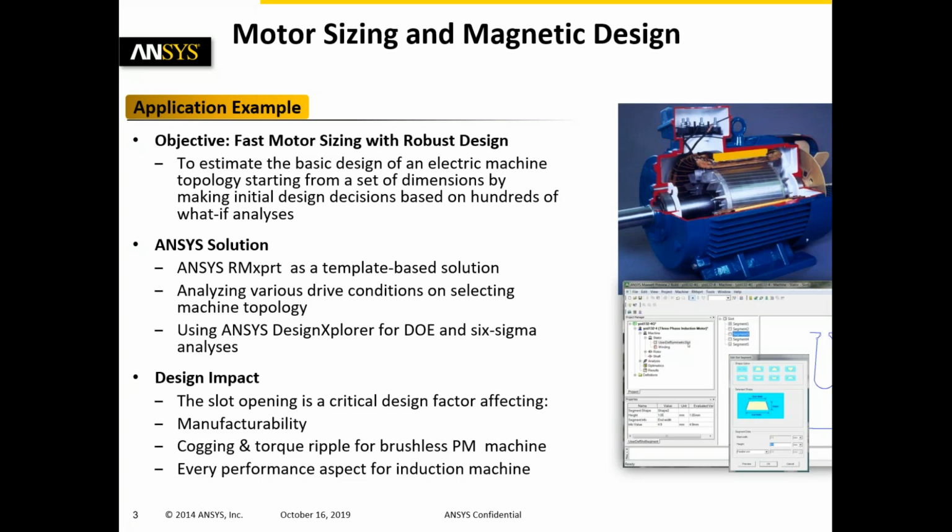for the motor. The impact of this workflow on the design would be the slot opening. Since the slot opening is a critical design factor, it will also affect manufacturability, cogging and torque ripple for a brushless PM machine, and every performance aspect for an induction machine.